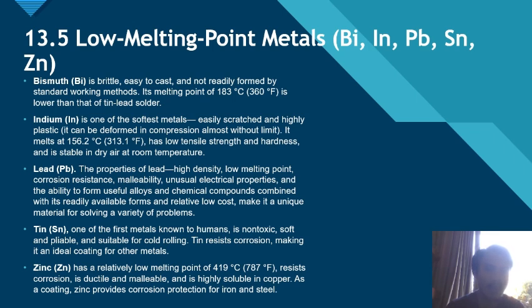Indium, In, is one of the softest metals, easily scratched and highly plastic. It can be deformed in compression almost without limit. It melts at 156.2 degrees Celsius or 330.1 degrees Fahrenheit, has low tensile strength and hardness, and is stable in dry air at room temperature.